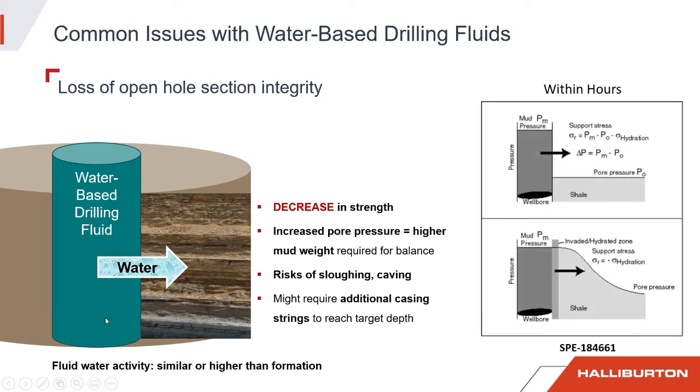The phenomenon is well documented as pore pressure transmission, and this happens shortly after exposure to the fluid. The invaded zone pressure rises to the mud column pressure or beyond it, so at that point there is no longer enough force to hold it back. Several SPE papers like the one referenced here give more details on this.